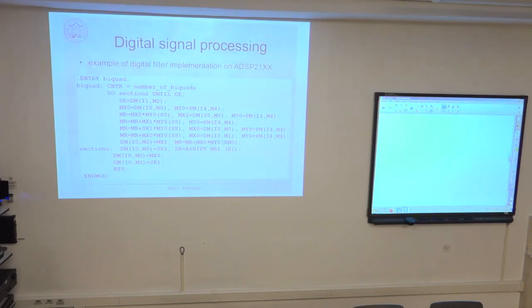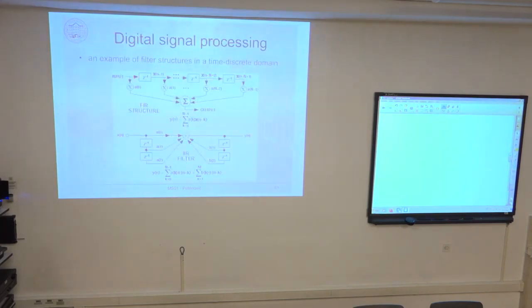But all of these operations that are depicted here can be easily performed in hardware as well. You must have hardware adders, hardware multipliers, corresponding structures, registers to store these state values. And the architecture of such a system is then called software-defined radio, although it is not really software.